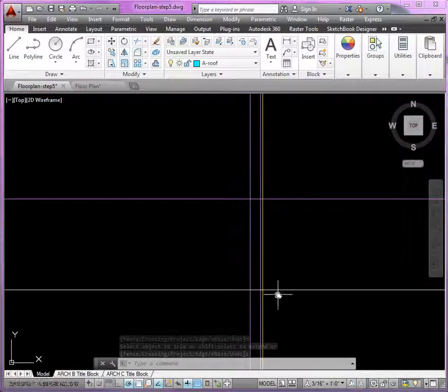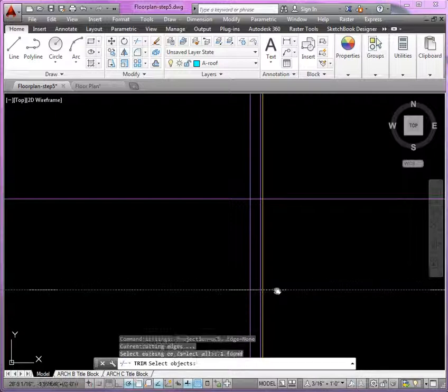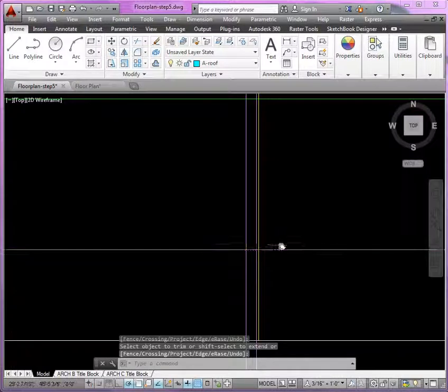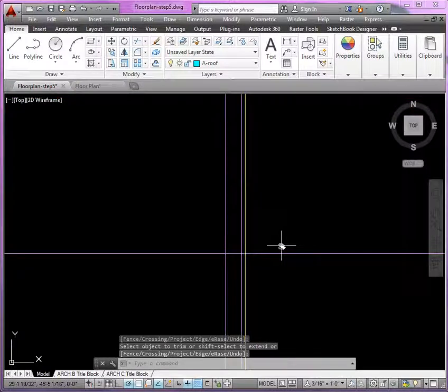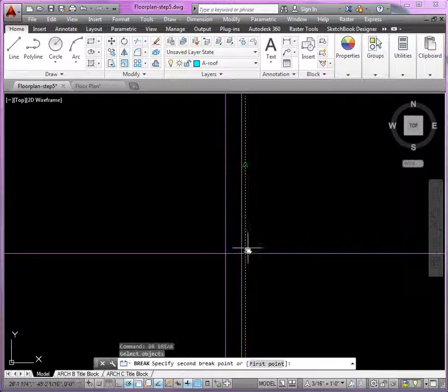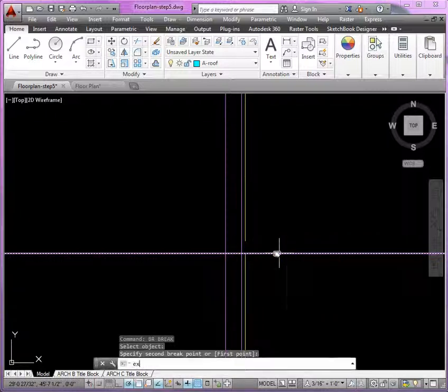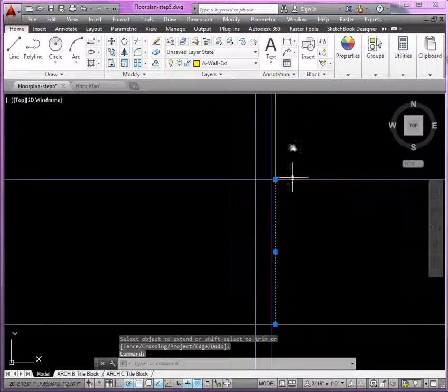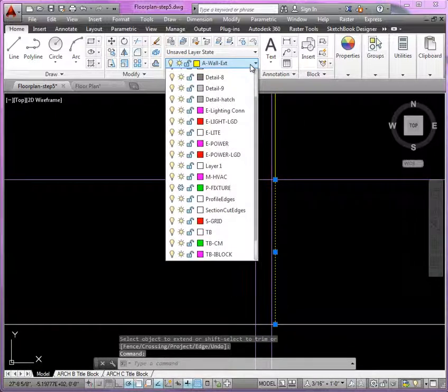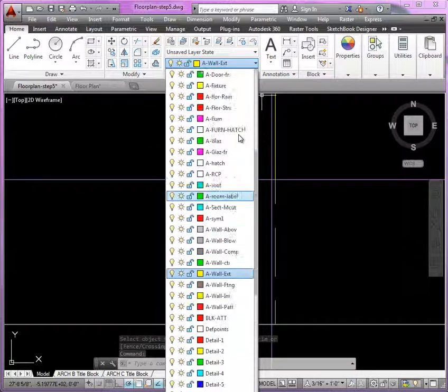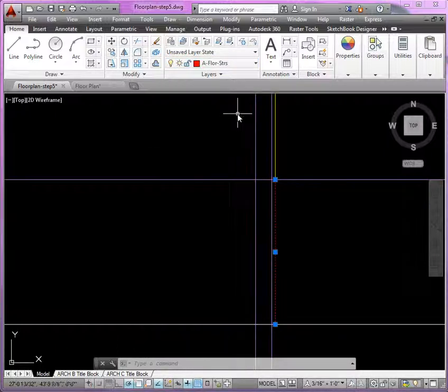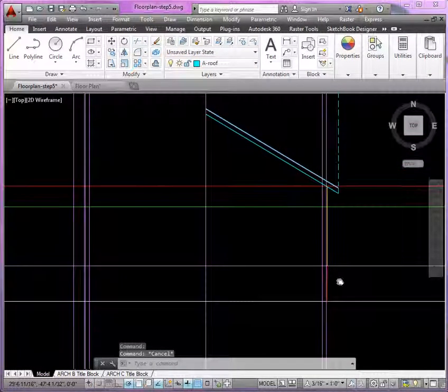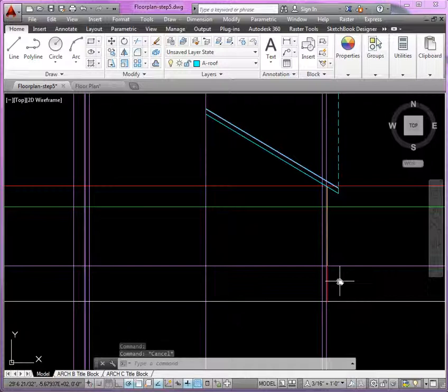And then down here at grade level, I can trim off the excess. And then here, if I wanted to show a little bit of difference in line weight, well, I could break the line. If I break it here, I could just simply extend it. This part would be represented as A floor stairs, right? This is the raised floor.